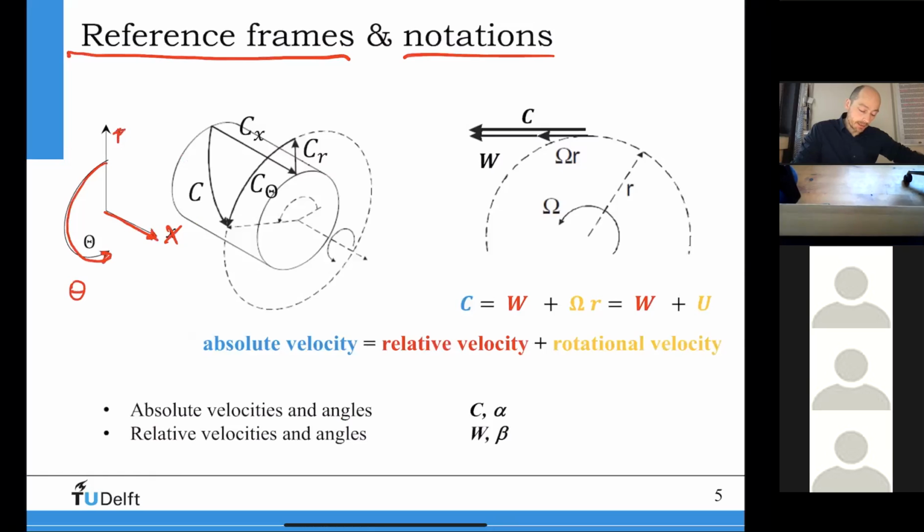Then you can see here this is a cylinder surface, right? Most of the time we use a cylinder surface for the turbomachinery that we are going to look at, because we are only going to look at mean design analysis, and we are going to neglect a lot of effects that happen in this first stage. One of the effects that can be neglected is that we can say the radial velocity is zero. I will discuss this later. So there's no radial component. The flow is basically only on this cylinder plane.